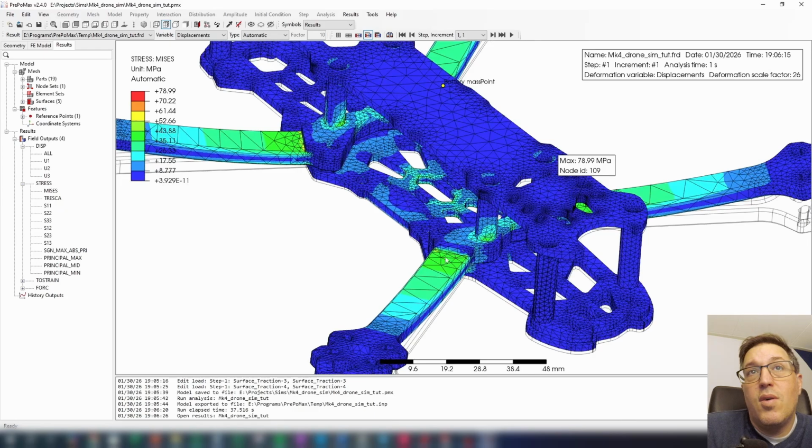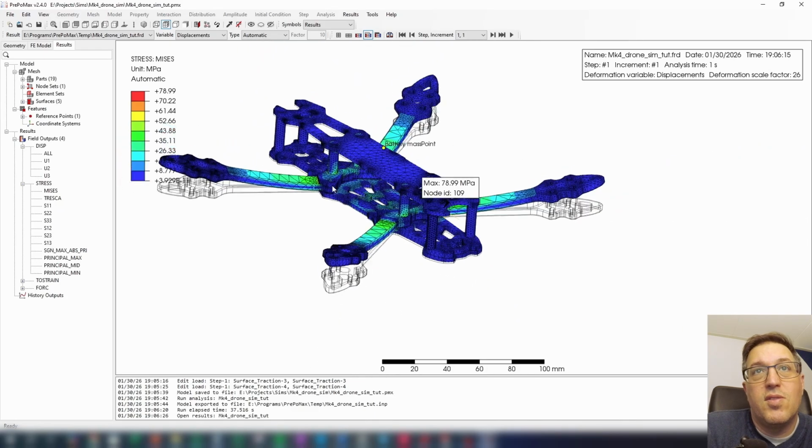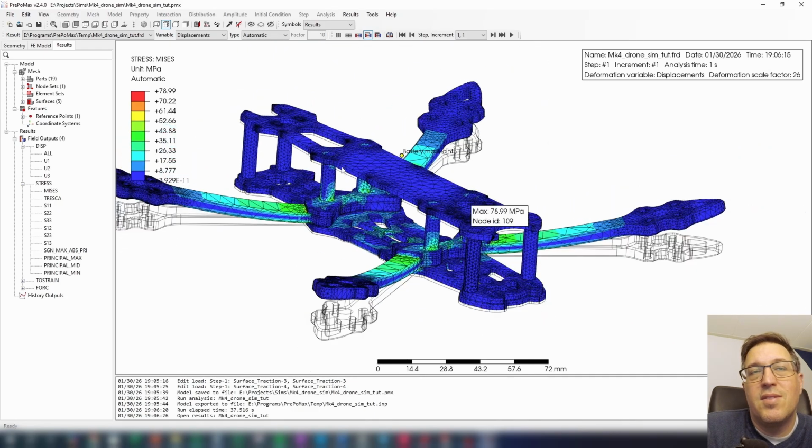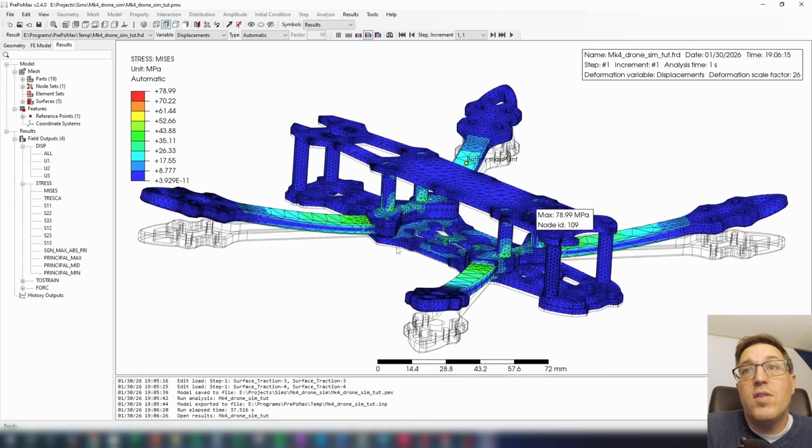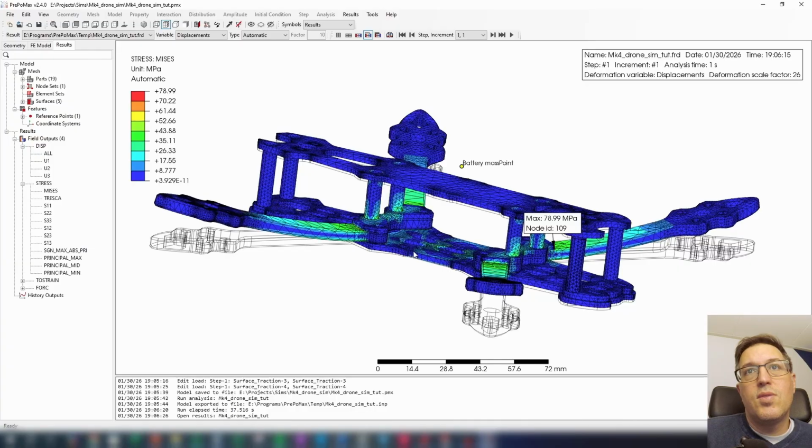Well, technically looking at these results, I feel very confident in continuing this design if I was the one to design this. And this is the end of this part. And the next thing is to make sure that this design complies with frequencies, or what kind of frequencies this thing can resonate to, because this system is exposed to a lot of vibrations. So the next thing is, of course, doing the modal analysis.